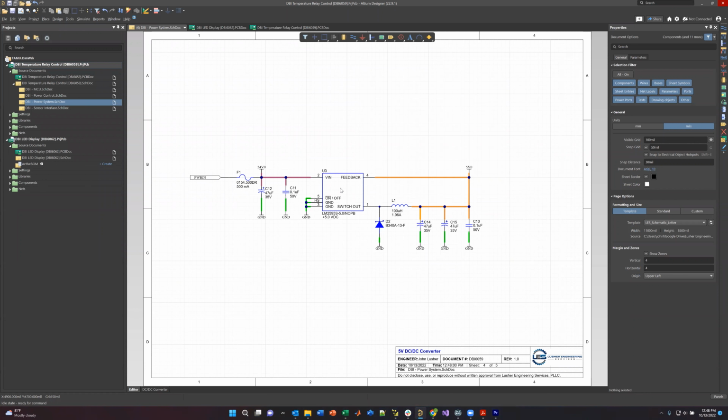So it doesn't matter. Years ago I actually would put in the exact voltage, like if I was doing 3.3 volts, I used to do this on a lot of designs. Nothing wrong with that. I just over the years have adapted this as my format, where I label my voltage as 24V0, with the V being the replacement for the decimal point. That's just what I do.